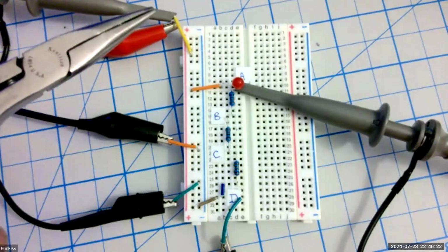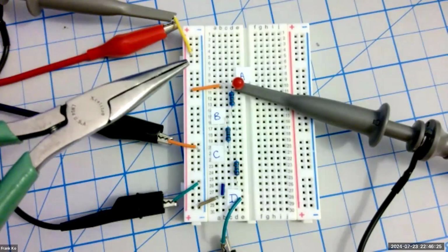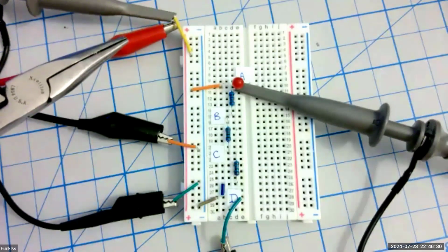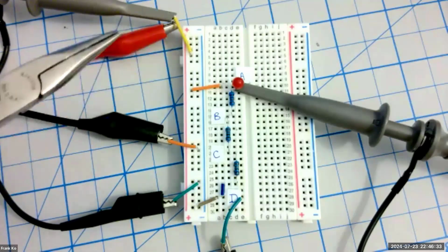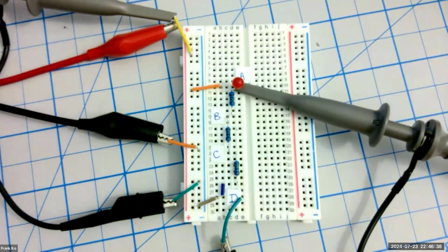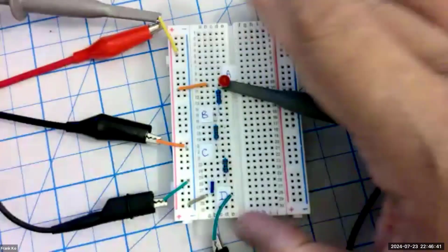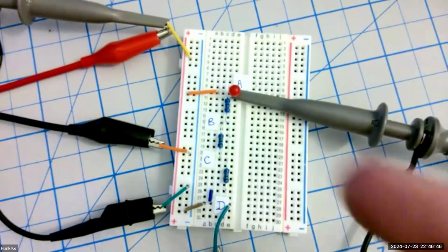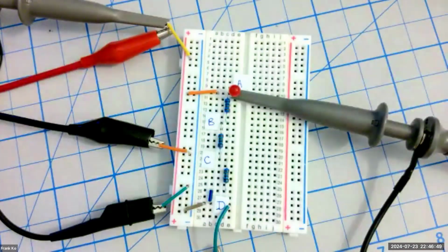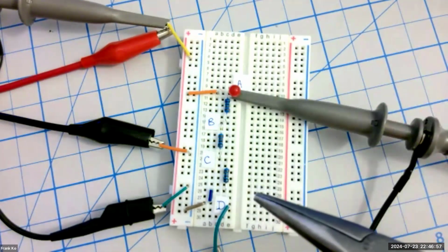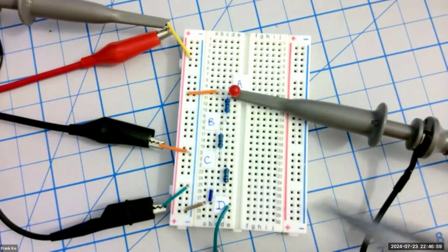So I've got 2 things connected to this input coming in. One of these connectors, this red alligator, is my signal source, my function generator part of my tablet. This probe is my channel 1. So channel 1 is connected to my signal source. So I'm verifying my signal source. My signal source is supposed to be 1 kilohertz. And this probe will determine graphically whether or not I am at 1 kilohertz. The probe will also tell me, am I at the desired amplitude of 3-volt peak or not?